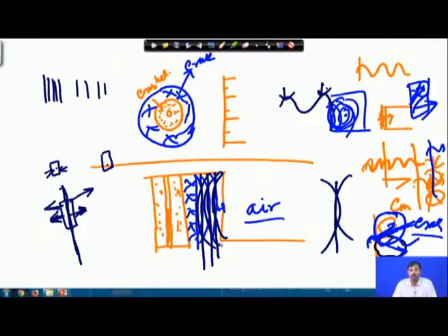Basically, we utilize this phenomenon of shock energy released ahead of the gases. As the shock energy is released from here first, it immediately cracks the crushed zone, then the shearing zone, then goes up to this point and returns back from here, creating tensile cracks prior to the release of the gas energy. So, what is our objective?